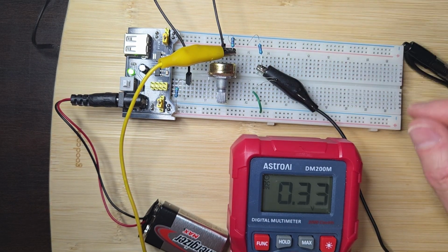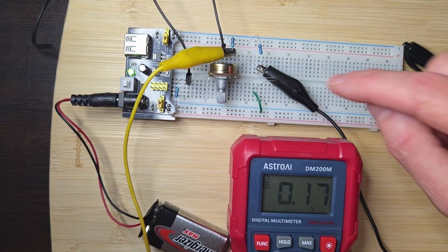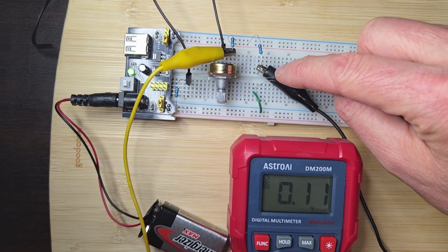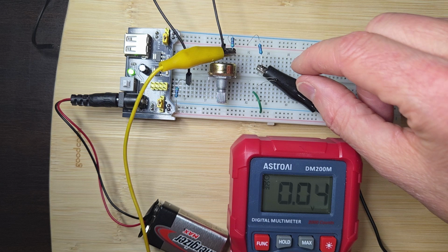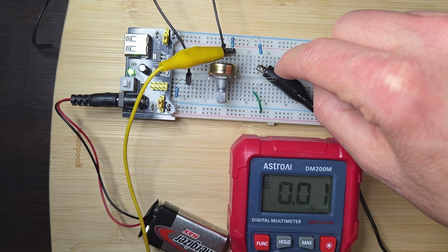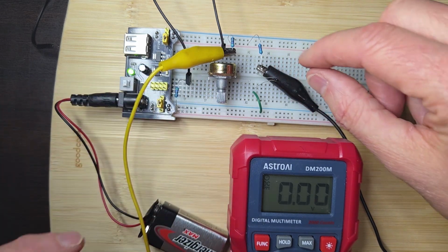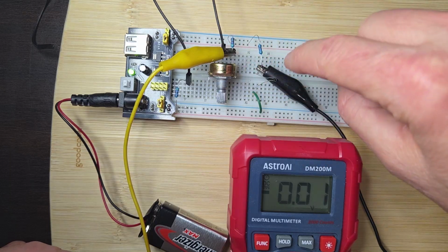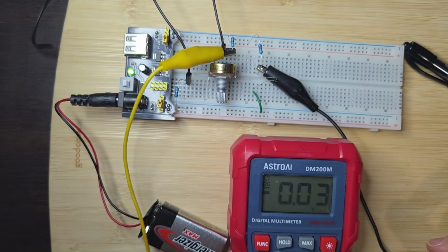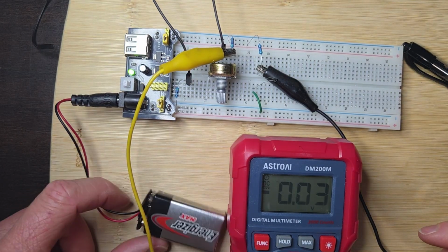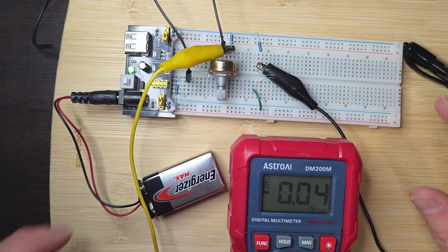But anyway, that's the basic function of the Wheatstone Bridge, is just to know what this resistance is. And when it's 0, we could literally measure that. Of course, if I picked it up, it'll change it, but I could measure all these, and these 2 branches at 0 volts would be the same ratio. So really neat, and very useful even today.